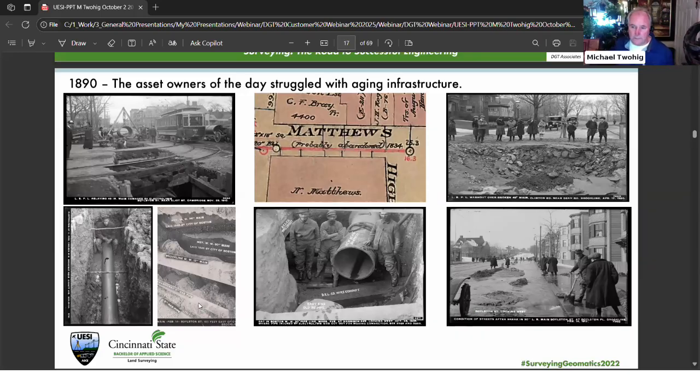So we actually did find that there were several places where, with our radar system, we were able to identify several layers of utilities, which is problematic if you've ever used a pipe locator that you're tracing and you keep tracing in the same place. You're always chasing, did I get a good ground? Maybe I'm grounded. Maybe the signal is bleeding off. But then when you go back with the radar, you say, I'm not an idiot. I'm actually still doing pretty good, but it's just the site conditions are challenging.